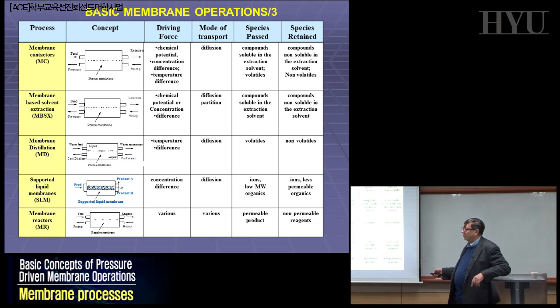If you are able to control some parameters in the feed solution and in the permeate solution, for example a different pH, you can create a situation in which at a certain pH, the complexing agent that you immobilize in here will interact with one metal, cadmium, and will diffuse across, because now we have a difference in cadmium complex concentration, and we release at a different pH.